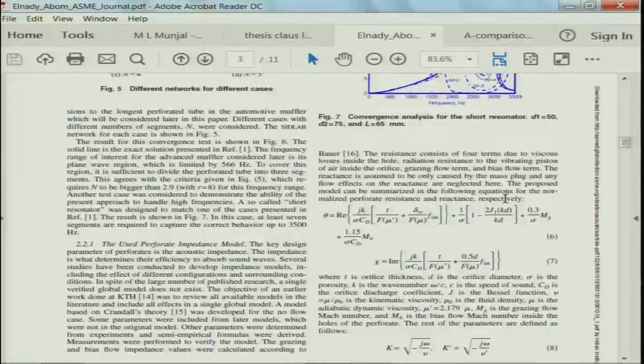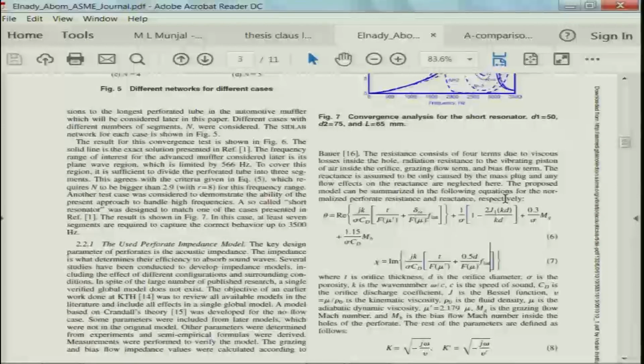They can be perforated mufflers, very complicated ones like the one the photograph showed in the beginning of this lecture, where you have a 4 duct interacting system, 3 perforated pipes and the big annular cavity which contains the 3 perforated pipes, inside an elliptical or circular cylindrical shell. So, it is a multiple interacting duct problem with multi path propagation.